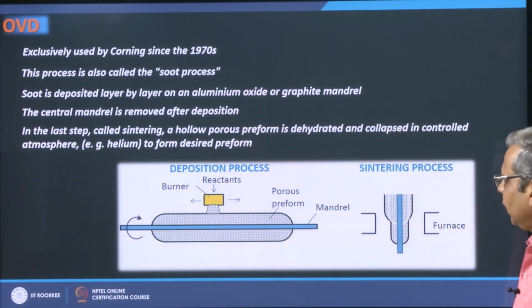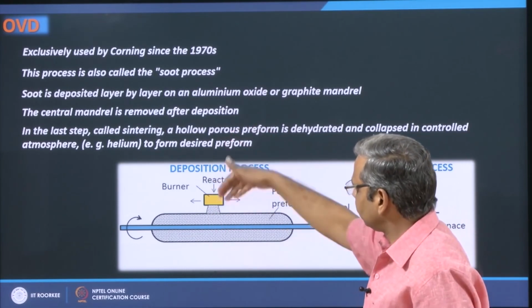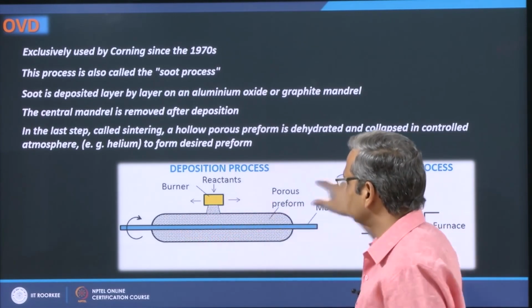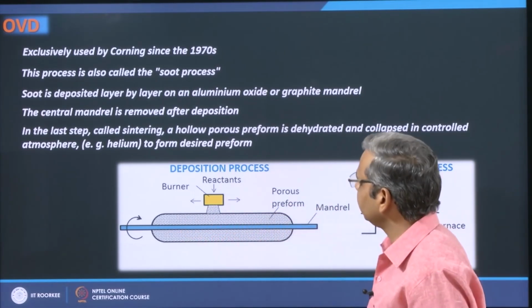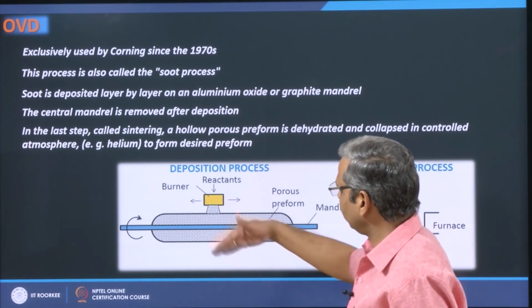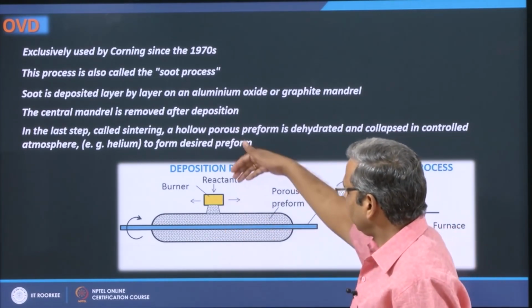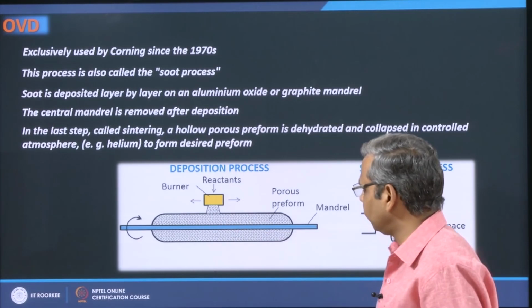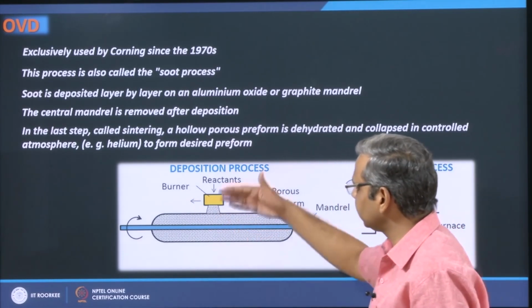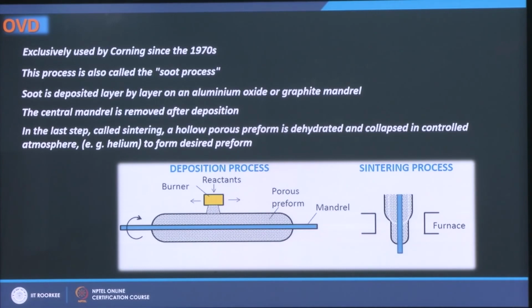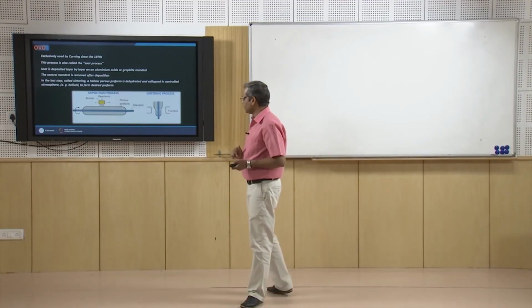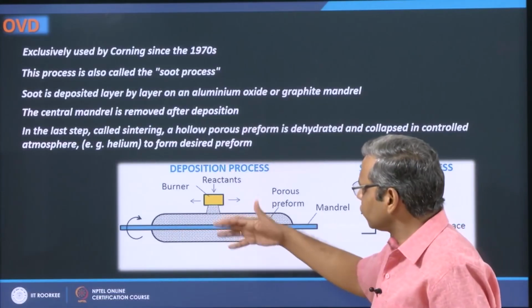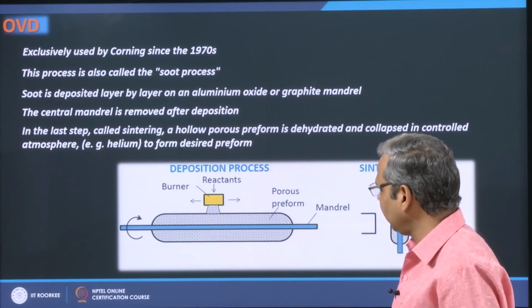So, when fiber comes out of the draw tower, it looks like this, which has got a core, cladding and acrylic coating. Then it can be put in the form of cables. So, this is the fiber, then you put a jacket onto this fiber, and in between you put some cushioning using aramid fibers. Popularly known material of this is Kevlar. Using this you can now either make submarine or telecom cable, or you can make patch cords.